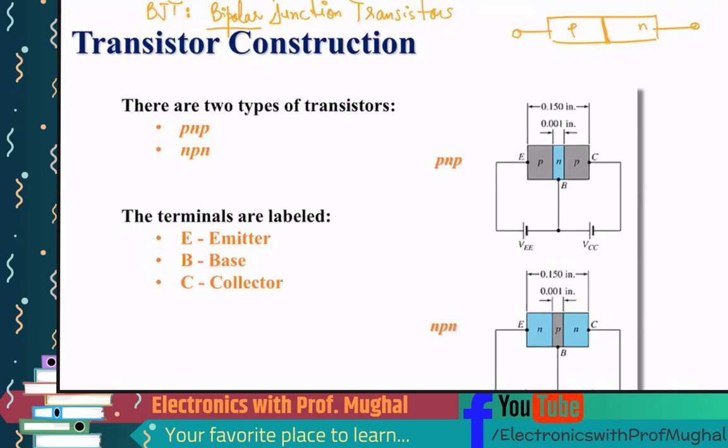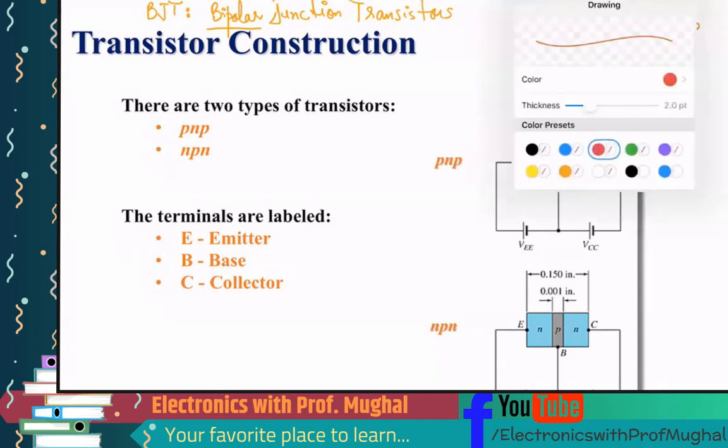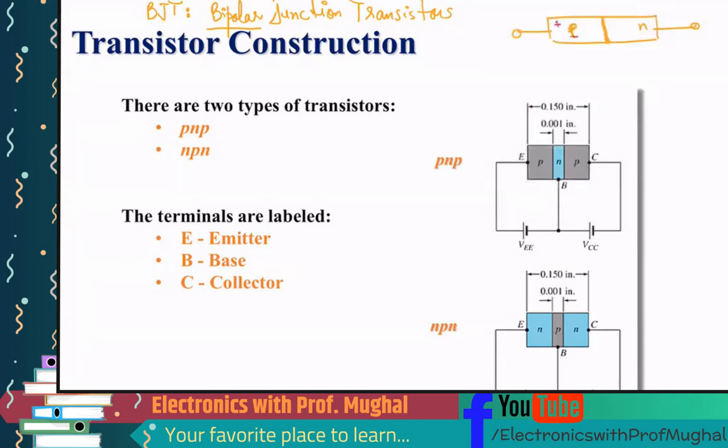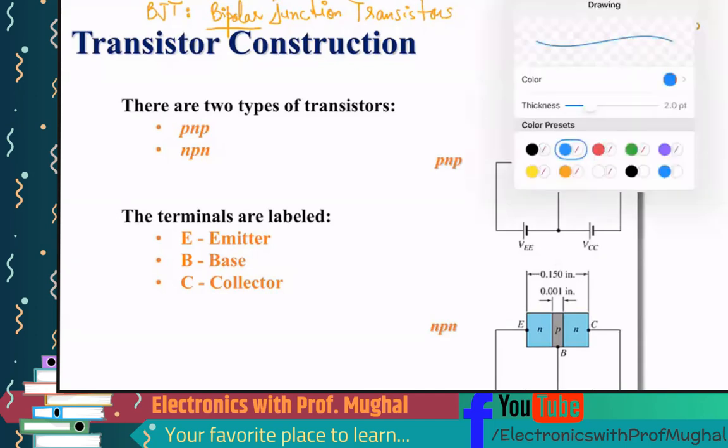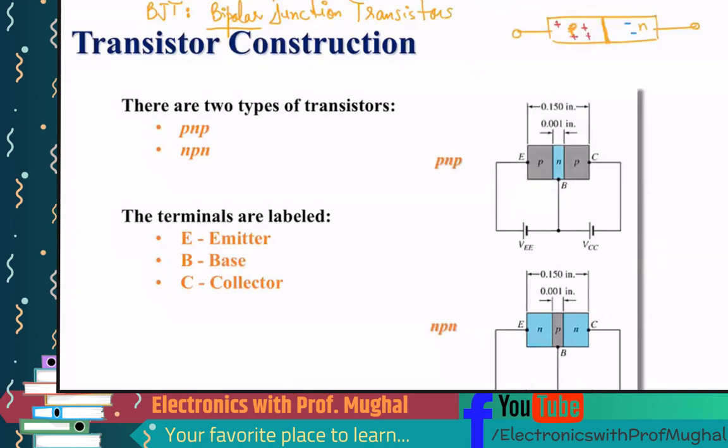Across this diode, because this was a p-type material, it had a lot of holes in there, correct? And here you had a lot of electrons because this was negative. Because of the force of attraction between the two opposite charged materials, these electrons will move here and make a wall like this.